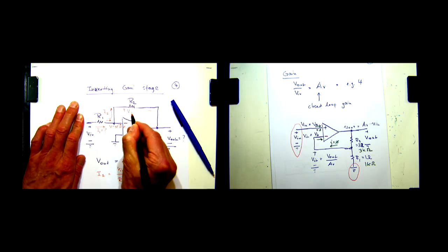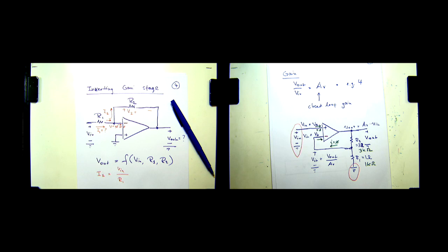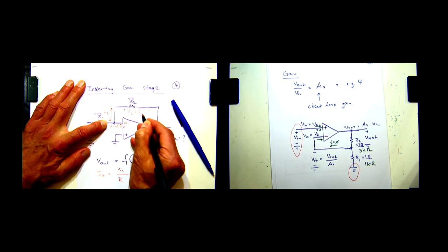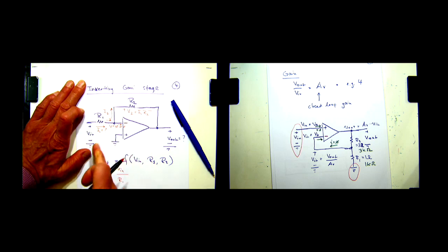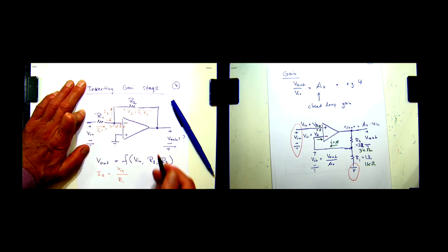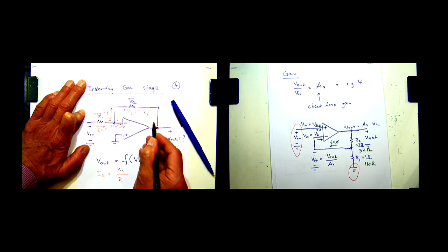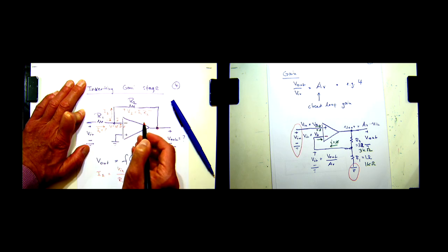So, what's the voltage across the resistor? Let's call this voltage V2. Yes? Okay, yeah, you're absolutely right. It's going to be I1 times R2, right? And then, of course, we can plug in for I1. So, what is the voltage here? That's the only tricky part. The voltage here is 0. The voltage across here is V2.